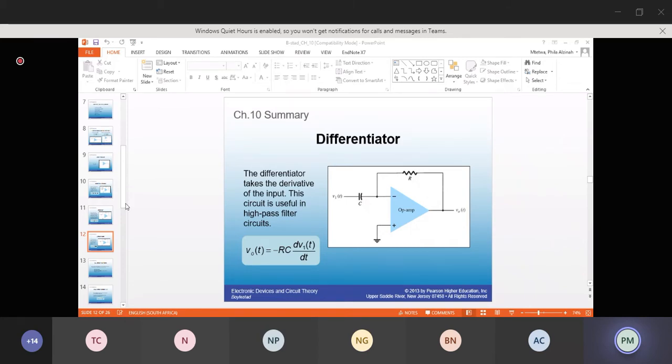It's also important to be able to identify the components. If I ask you to show me a transformer, show me a transformer. If I ask you to show me that bridge rectifier you're talking about, be able to identify those diodes that are working as a full wave bridge rectifier. Some of you will show me the diode after the regulator. That diode is just there to ensure the correct polarity. It's no longer rectifying. You cannot rectify and rectify again.